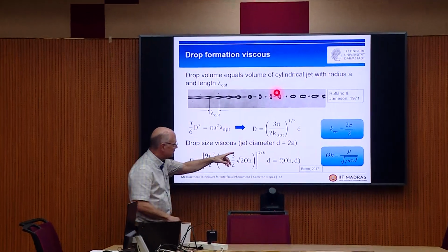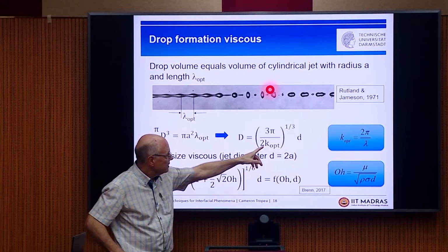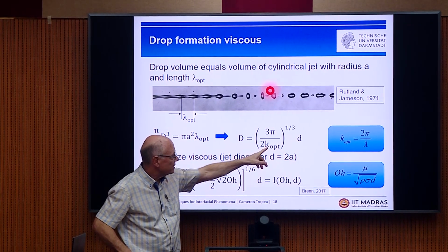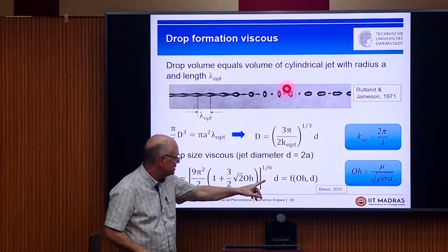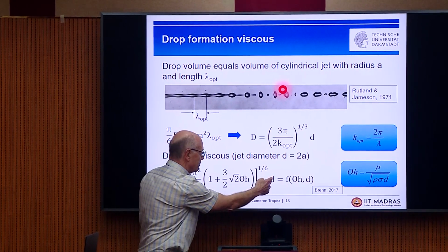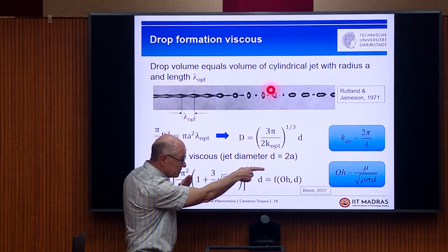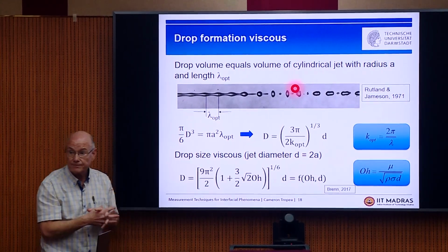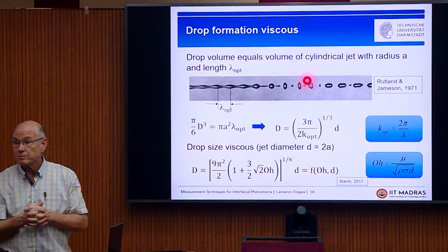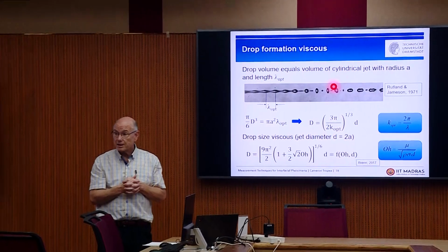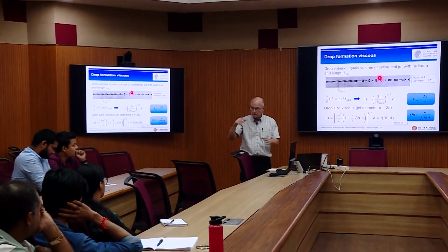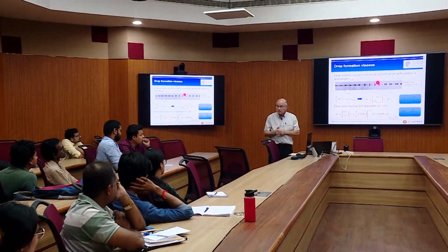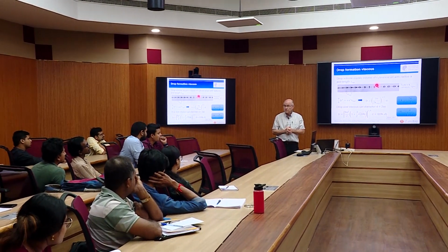But if we take a slightly different derivation to get the other K optimal with viscosity, then the drop diameter is equal to the diameter times that. And that has the viscosity in it, so it changes. Yeah, and this was done by Weber, and Brenn has derived that very nicely. I didn't do it; it's more complicated. It takes longer, but this changes for a viscous fluid.